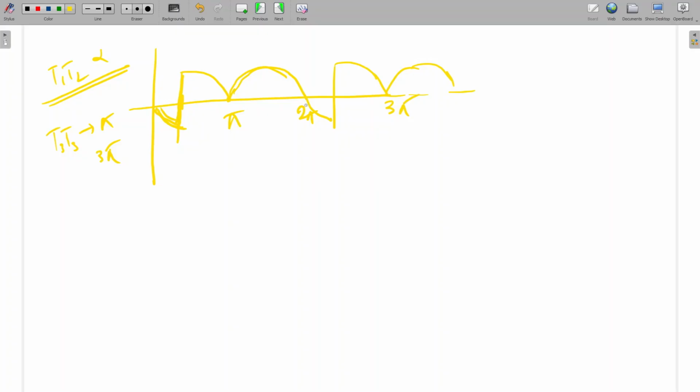Let's say this is alpha, this is 2 pi plus alpha. Like this a sequence can be given. So the waveform will be like this. This is alpha, this is pi, this is 2 pi. So what will be the average output voltage? We have to integrate from here to here. That will be one cycle. Is it clear? You can explore this kind of thing. Is it clear to all?